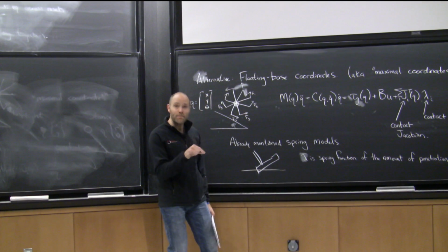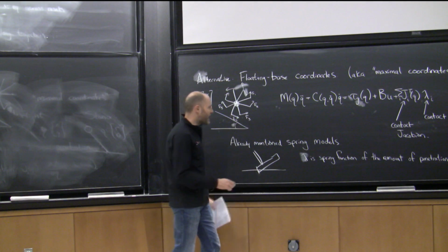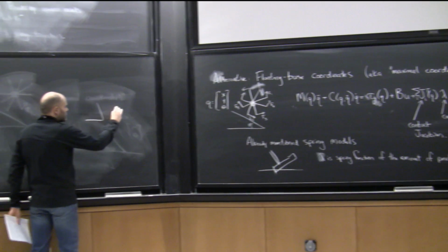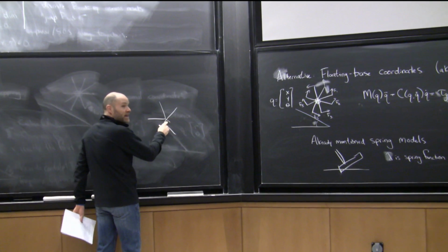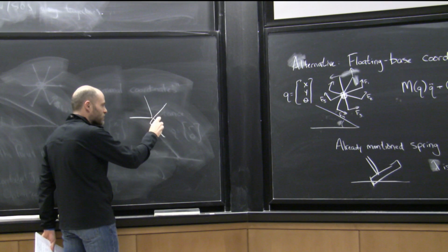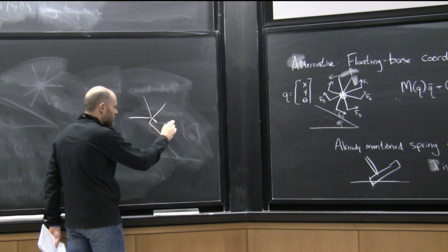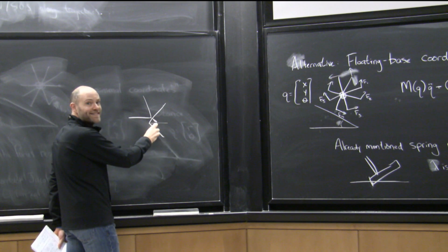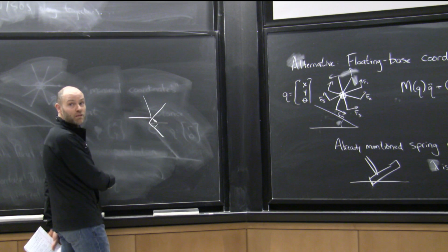But once you have any penetration, it gets very hard to maintain numerical accuracy, because if you have, for instance, two bodies in contact and one somehow penetrates, it's very possible to enter this space where you're trying to build a spring model, and then you just happen to cross a threshold, and suddenly you're ejected out of this space that you were never applying forces against.